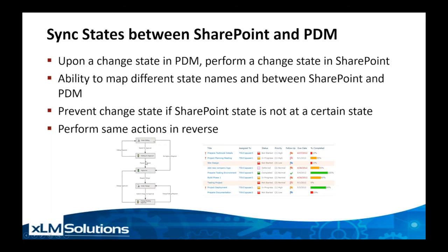We can prevent doing a change state in SolidWorks PDM if the corresponding data in SharePoint is not in the right state. And these can be in reverse. So we can have PDM sort of control SharePoint or SharePoint control PDM, to control state synchronizations between the two systems.